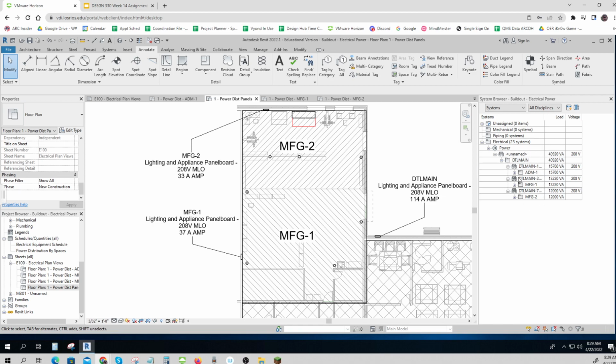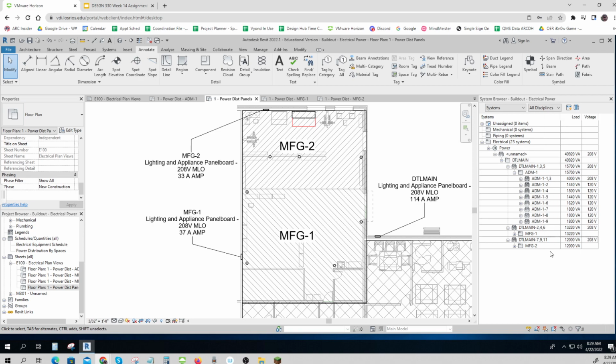If I want to find out what's going on in there, I go, oh, look, I've got all these other circuits. And there's circuit breakers in there. And this one happens to hook up to circuit 1 and 3. And if you've done some electrical, you know that that's because it's a 208. So that goes across 2 of the legs, whereas your 110 goes from ground to 1 leg. Okay, but there's circuit breakers inside that panel.